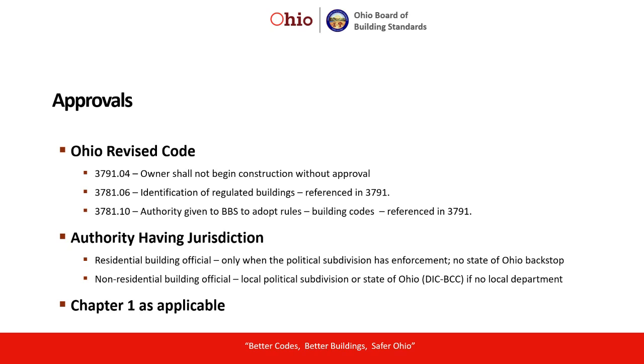So that's a lot of information crossing back and forth, because residential buildings can be regulated under the residential code, and residential occupancies can be regulated under the Ohio Building Code. Buildings and structures can change occupancies and move back and forth between them. They may visually on the outside look like a single family dwelling. You may want to think they are a residential building and that would be regulated by the Residential Code of Ohio, but you have to drill a little bit deeper. You have to have an understanding of the intended use of that building, and it's possible that it will be regulated as a residential occupancy under the Ohio Building Code instead of a residential building or dwelling under the Residential Code of Ohio.